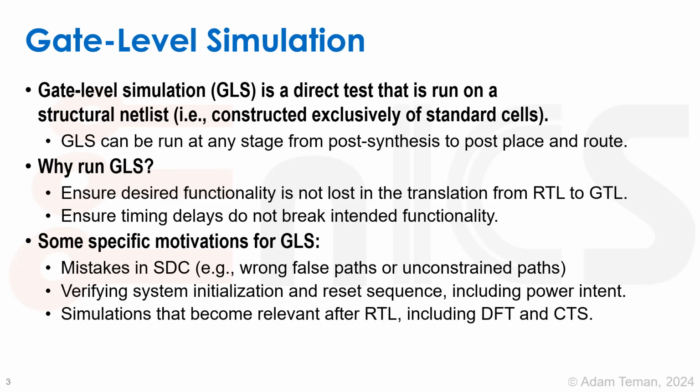Okay, there are some simulations that only become relevant after we wrote our RTL. We ran simulation and verification when we started, at the RTL level, and everything was behavioral. But now we've added all kinds of things after running the whole place and route, for example, design for test structures and things with our clock tree, which may have been ideal before that.